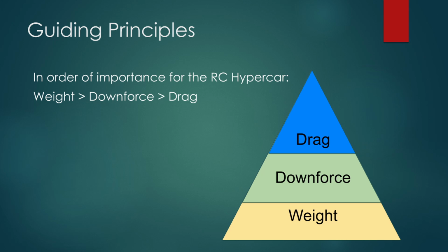And within reason, drag doesn't matter because the car has more than enough power. It's really overpowered when you look at RC cars compared to even full-size race cars. It does affect battery life, and the motors currently pull over 600 watts at 60 miles per hour. So heat is also a factor. So, reasonably you want to keep drag in check, but it is by far the lowest on the list compared to weight and downforce.